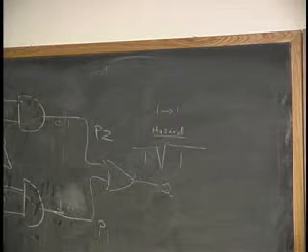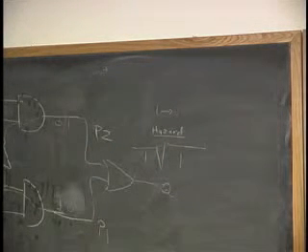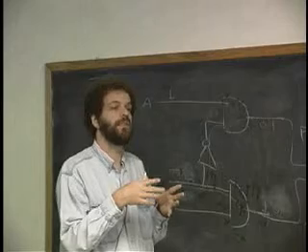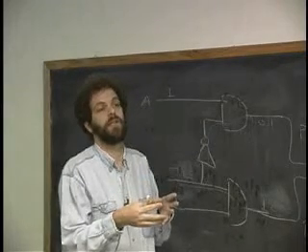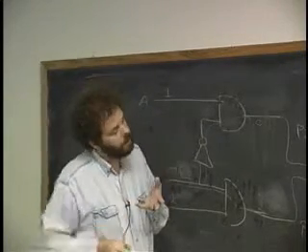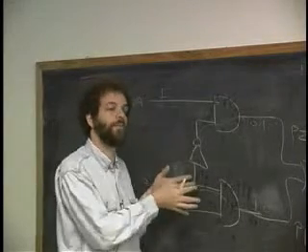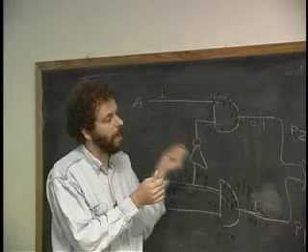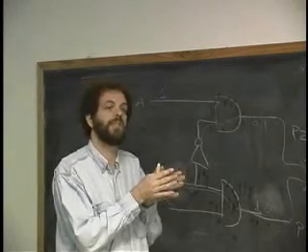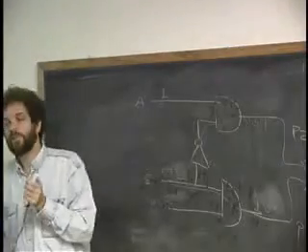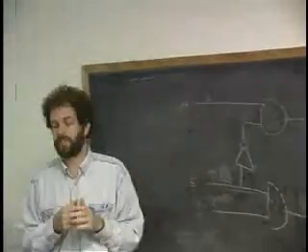Now, the reason I'm talking to you about the selector and about these hazards is that we're going to use the selector to implement a device which will then be used to implement the flip-flop or the register that we're trying to make. So I'm kind of building in this little section from the bottom up from the selector and how we understand how that works. And I want to understand the timing of the selector because ultimately we need to understand the timing of the flip-flop. So we all understand now, I think, that these hazards can happen.